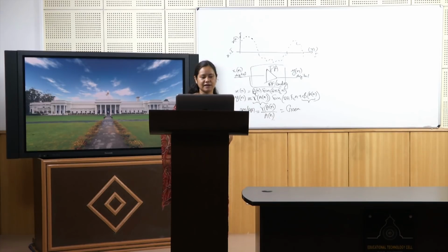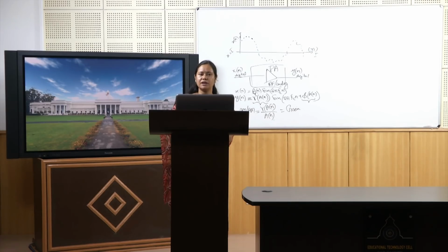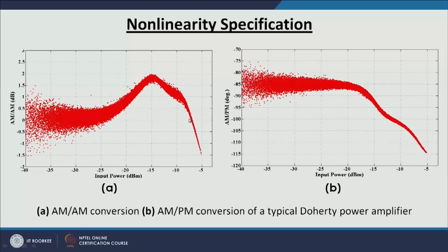When we look at this diagram, the gain was straight when the input power was very small. So, this was the linear region of the power amplifier. After that, when we keep increasing the input power, the output becomes nonlinear and saturated. In this particular case, it is a power amplifier with this particular nonlinearity profile. So, instead of a straight line in the gain, it has this kind of nonlinear profile after, let us say, an input power of minus 25 dBm.